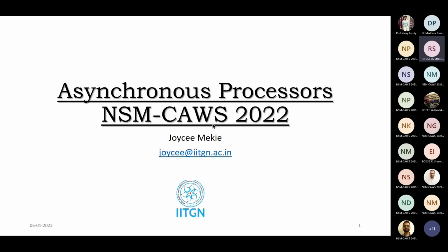When many such IPs are connected, by nature they become asynchronous with respect to each other because the overall global timing may be lost. So either the designer makes a significant effort to ensure that the global timing is known to every IP, or you just assume that everything is asynchronous, and then all the related hardware has to be in place so that the communication happens error free, right? This is the easiest example I can give for asynchronous processors.